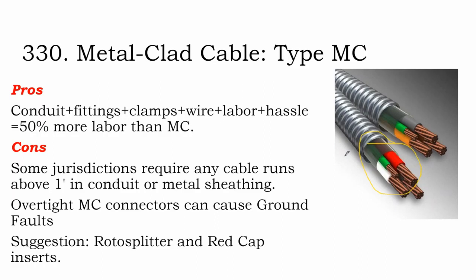And, in general construction, using a pre-made cable, if you can get away with it, it might cost a little bit more in material, but you make it up with labor. Now, the problem with solar cable specifically is DC solar cable inside of a building needs to be in metal. And so Romex does not work with solar for running cables through the inside of the building.